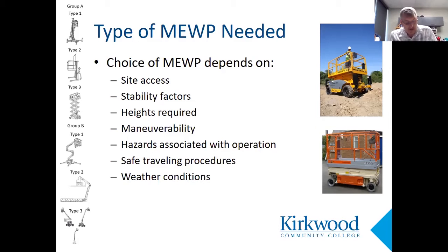Safe traveling. Again, how far am I going to have to drive? Any obstacles, any surfaces? Weather. Our weather system's gotten a little bit better. Pretty much can predict where we need to take cover with shelter, sometimes in some places right to the minute when the storm's going to hit. But our weather conditions in determining the MEWP, is it cold out, is it going to be hot? Some other additional information is how the lift is going to need to be powered: battery, propane, or gas.